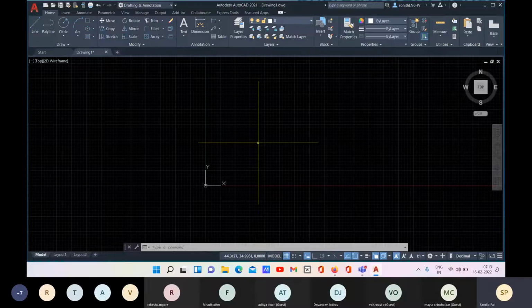In the polar also we have the same absolute and relative. If you are calculating from the origin, that is your absolute, and if you are calculating from the previous, that is your relative. That is the simple funda. And when I talk about polar, that means you are calculating the angle, or in the 360 direction. You are locating a position with the distance and in 360 direction.